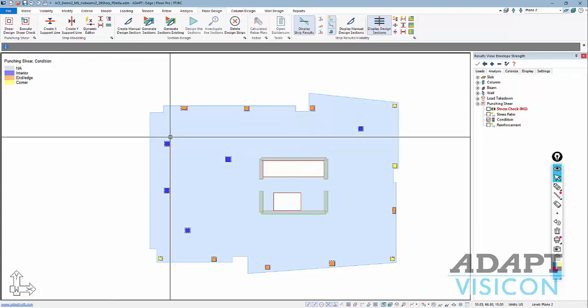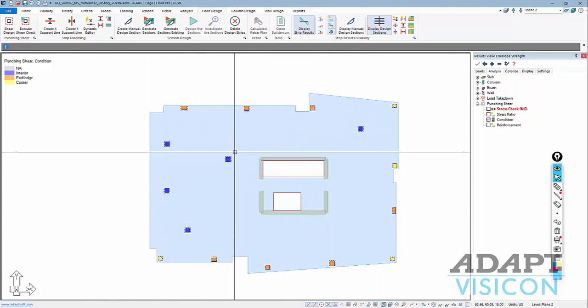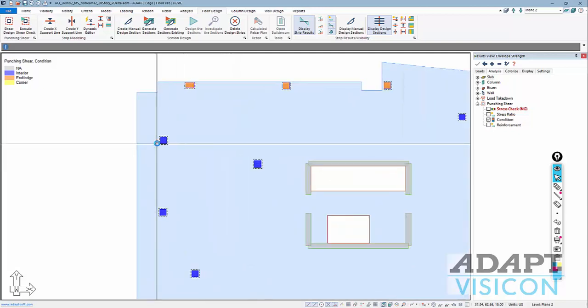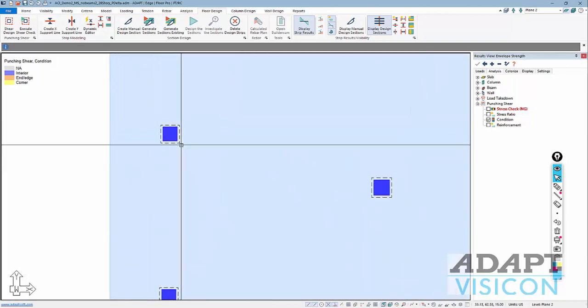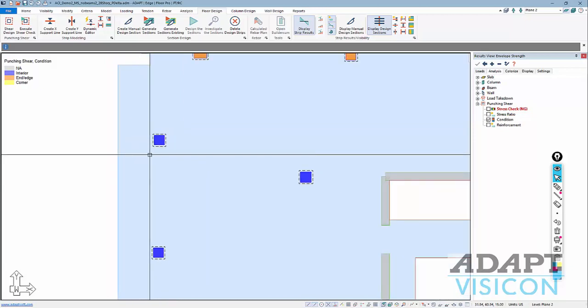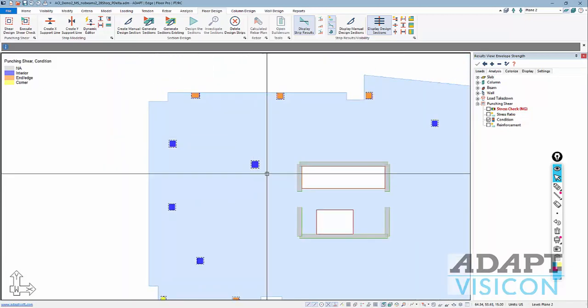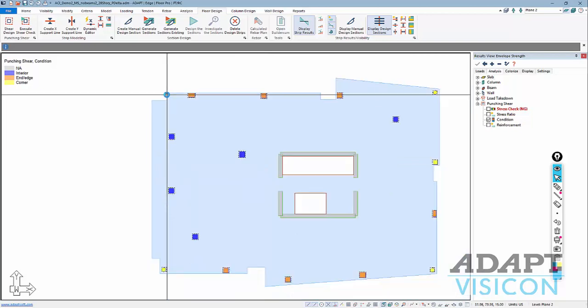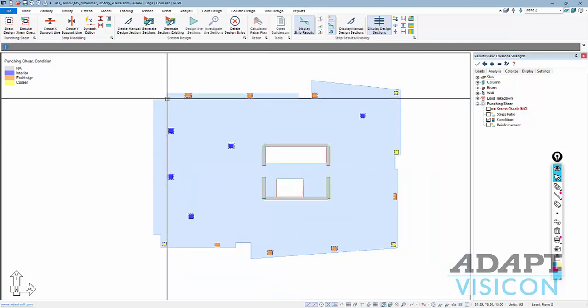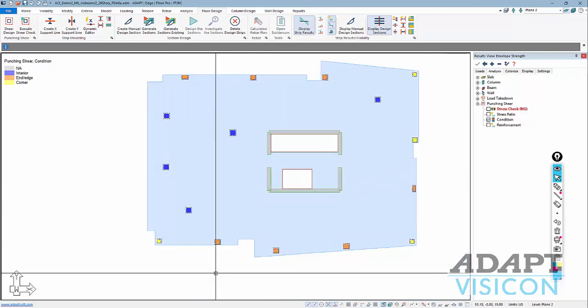So most of these, the interior columns, are obviously four-sided, they're interior. This just gives an indication of the critical section shape that we're using at d/2 from face of column. This does not necessarily indicate every critical section shape, especially when we have the check made for the octagonal shape.